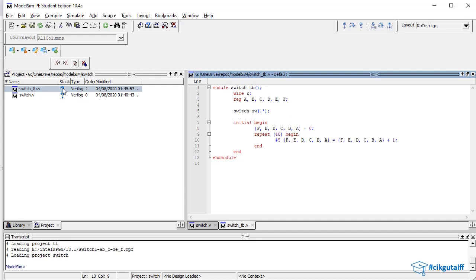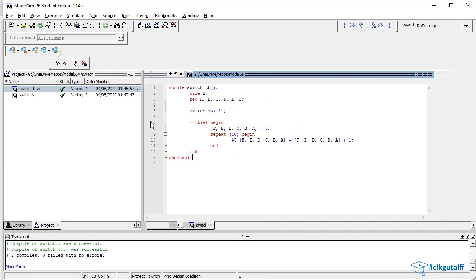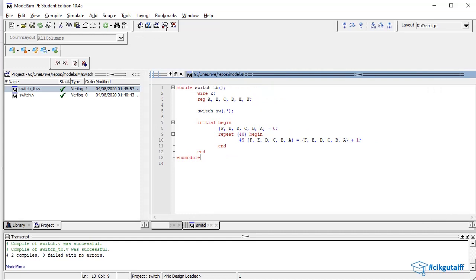If you notice, these files were just created, so next to the project panel here, it puts the status as a question mark because it hasn't been compiled yet. So I go up here to compile all, press that, and it will go ahead and compile all the Verilog files that I have here. If you notice here, there are no errors, so I get 2 green ticks to mean that there are no errors. So now I can actually simulate it. I'm just making this side bigger, so I can click on this button here to start simulation.